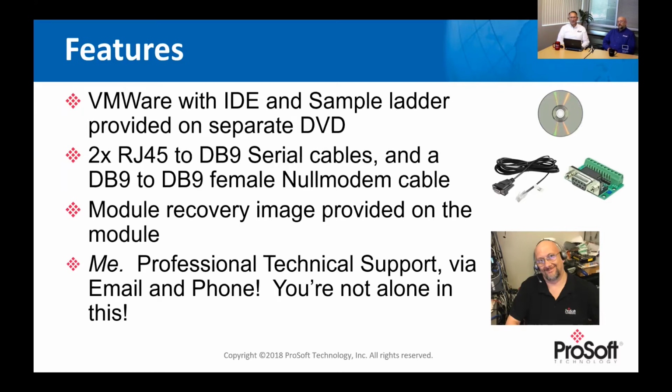And then if you look at our hardware, you notice that because of space on the front of our hardware, it's not easy to put your traditional serial ports that you see in the field a lot. We have these RJ45. So Larry, what else comes in there? Well, in the box you get two RJ45 to DB9 serial. That allows you access to the two serial ports in the ControlLogix module, and again in the CompactLogix module you get the two as well.